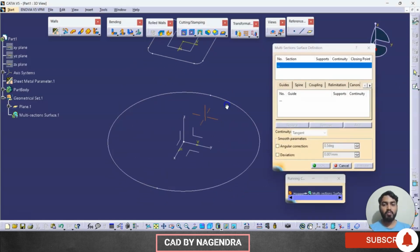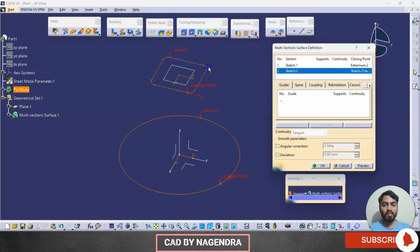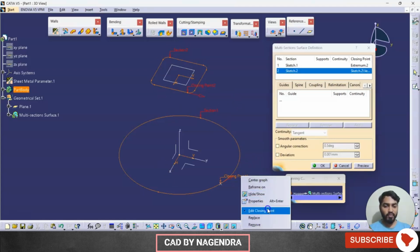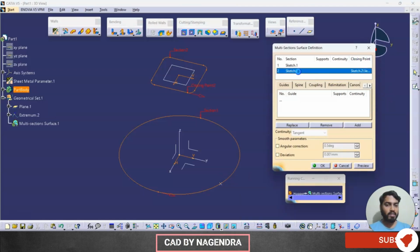Then the same options we used in create multi-section solid, the same process we will follow. First sketch, I'll select the circle where we need to create points. Then the second profile is this, because points are already available. Then the closing point on this circle, we just need to remove this. You can see that for sketch 2 a closing point is available, for sketch 1 a closing point is not there.